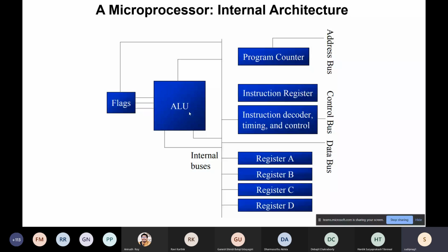So to speed up the process, people have come up with pipelining, where they keep another register on top of this instruction register where they store the next instruction, and once the instruction register gets decoded, it automatically copies the value over here. As a result, you don't spend time waiting while the memory address, control and data come, which takes at least a few tens of nanoseconds in most microcontrollers. Even those tens of nanoseconds are very expensive, very slow.